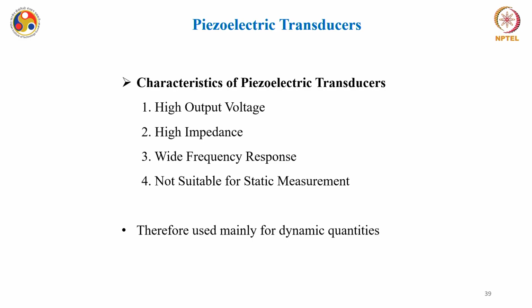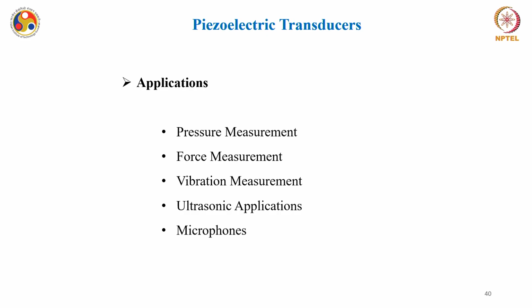okay. If you talk about the characteristics of a piezoelectric transducer, it has a very high output voltage and high output impedance, okay. It has a wide frequency response, and they are not basically suitable for static measurements, and mostly you will see that piezoelectric transducers are used in dynamic applications because the charge will vanish within time, okay. So you will see that piezoelectric transducers are mostly used for dynamic applications, okay. The applications can be like in pressure measurement, force measurement, vibration measurement, say for ultrasonic applications, microphones and so